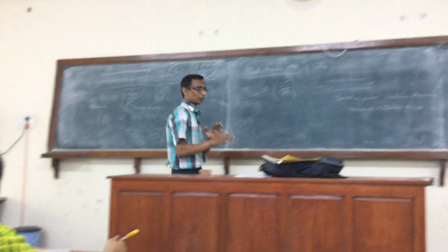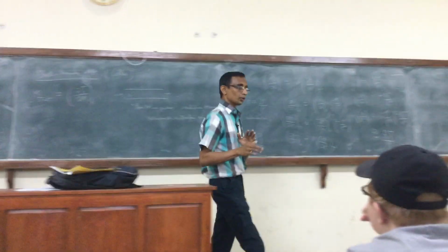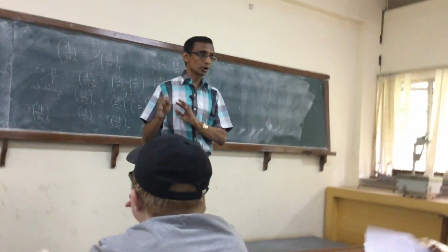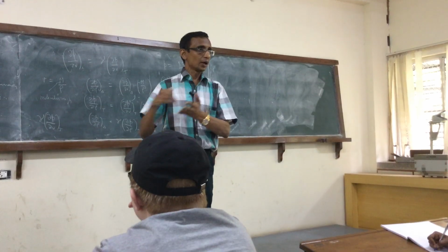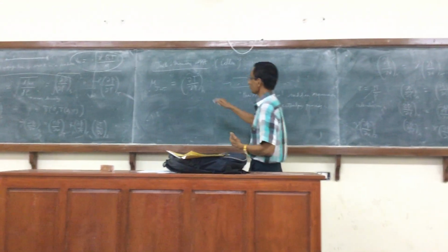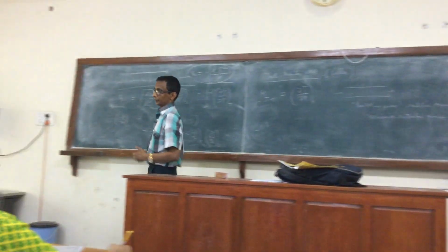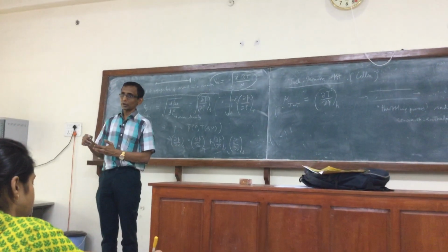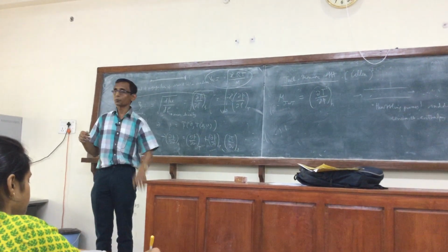So if I want cooling, I want conditions such that the Joule-Thomson coefficient is actually greater than 0, because the whole purpose is to reduce the temperature. We are doing an expansion process, the pressure will decrease, and the temperature will also decrease when the Joule-Thomson coefficient is positive.